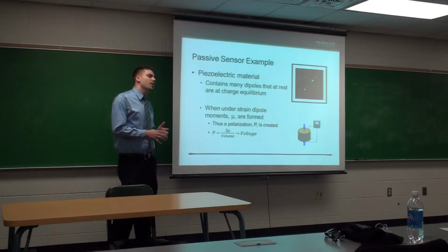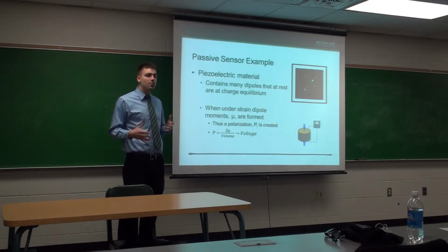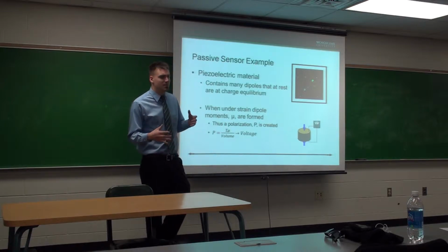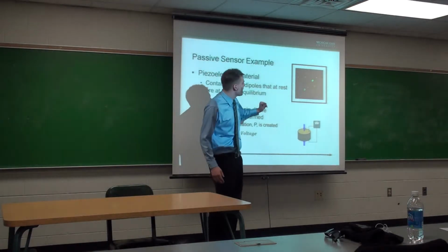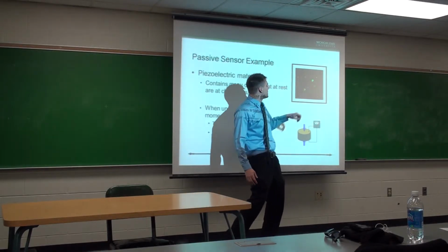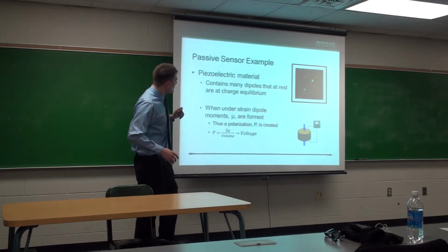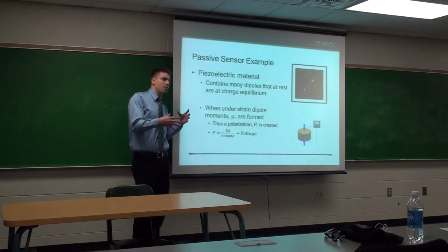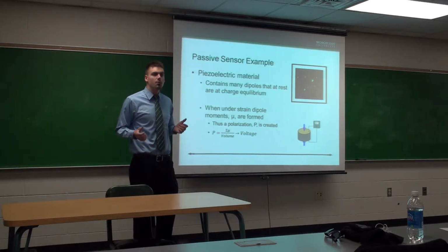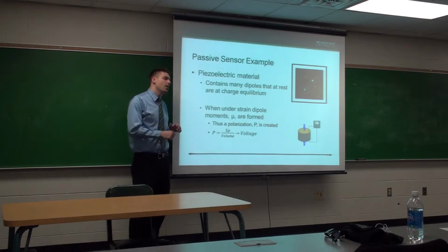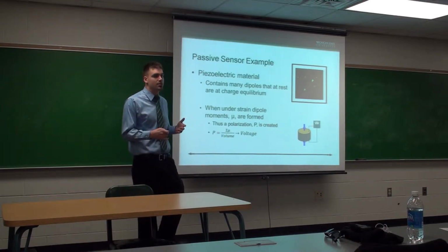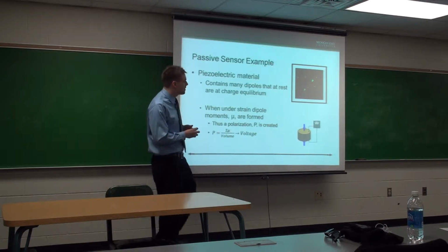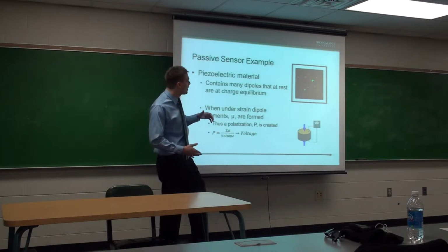Piezoelectric material is a specific type of material that contains dipoles that are oriented in a very specific asymmetrical pattern, such as shown over here, if you imagine these green balls to be dipoles. While at rest, these dipoles remain at charge equilibrium. However, when the material goes under strain, and these dipoles are physically forced to move, dipole moments are created, and this polarizes the material itself, creating a potential difference from top to bottom, say.